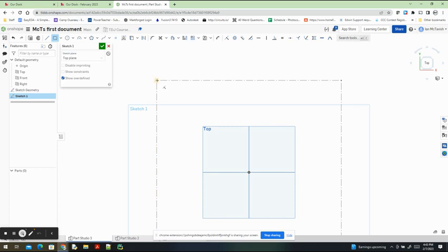So there's that point. I'm going to click, that's going to start the one corner of my rectangle. And when I hold my mouse over here, I get orange. There's my other point. Now, I want to be very careful here because if I change this measurement that's currently selected, I'm going to over constrain it, because my distance is already set based on it having to touch this point in this line. So I don't want to change that. I'm just holding my mouse over the other one. And now I can type 1, enter, and I'm just going to use escape on my keyboard so that I don't need to enter this dimension.